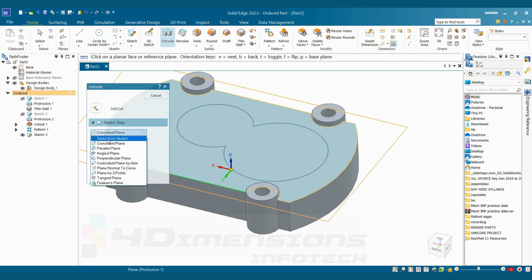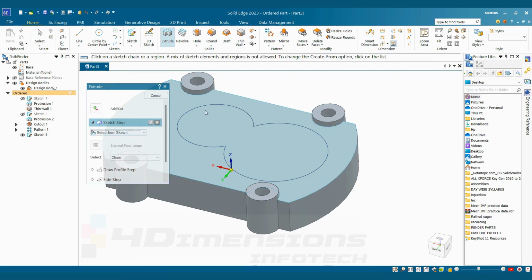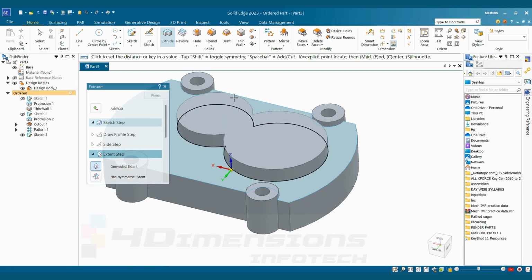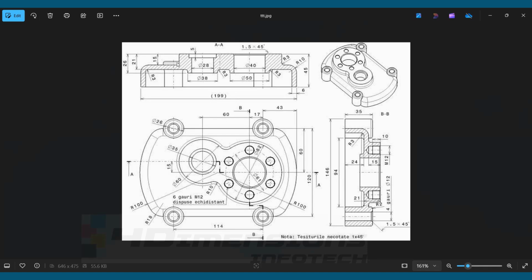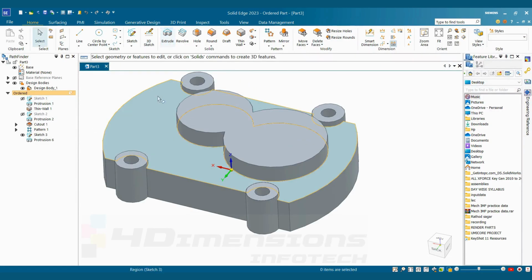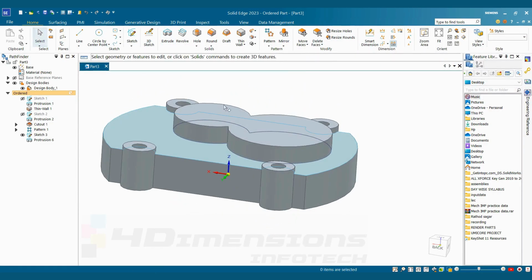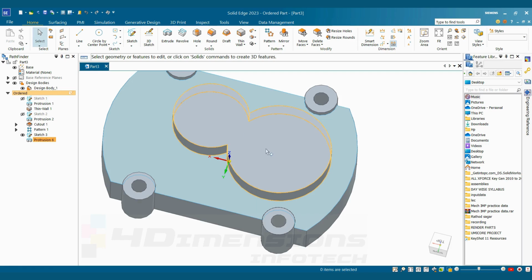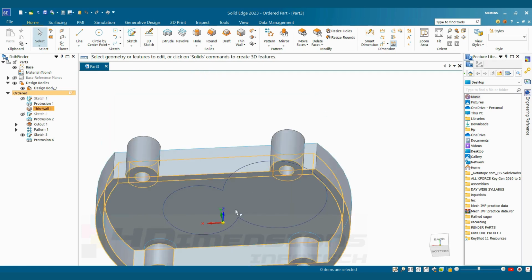Select the option as select from sketch. I'll select this sketch and say OK. Now the extrusion height here is given as 15 mm. You can see here, this above extrusion is of 15 mm. This shape. So here I am going to say 15 mm extrusion. Next, two more extrusions are required here with the same centers of these two circles but at the bottom side.